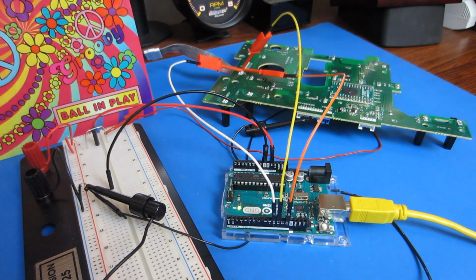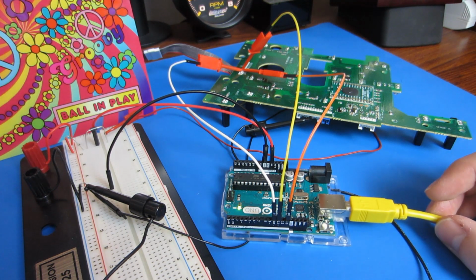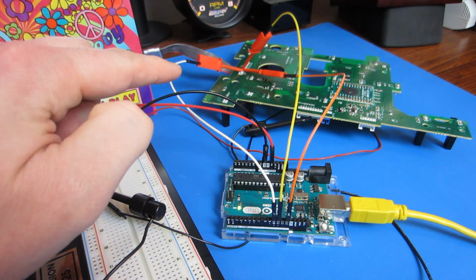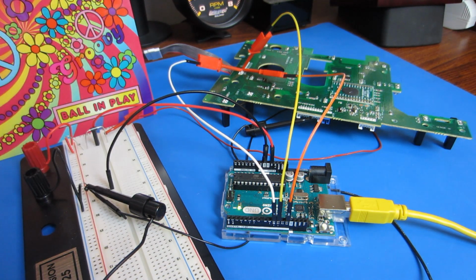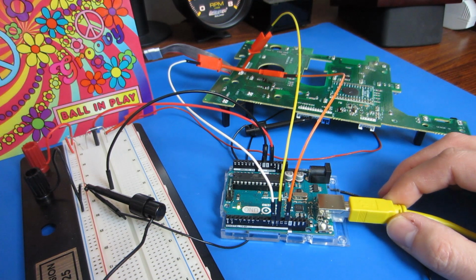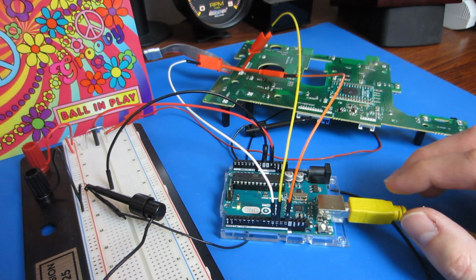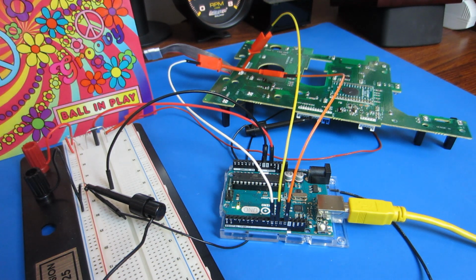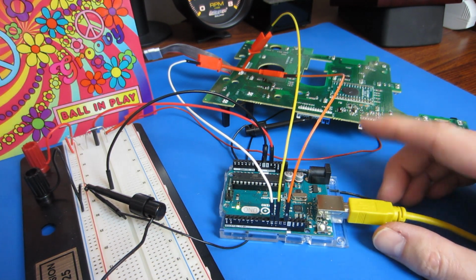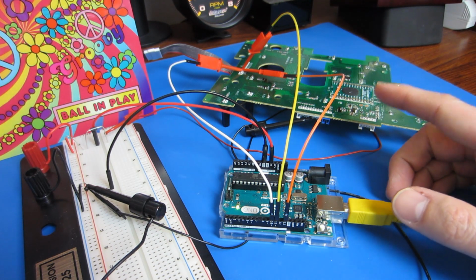I've changed the way the system is powered. You can see I've got USB plugged in. This is going to my PC. I don't have a power supply connected to the breadboard anymore. In fact, the breadboard and the playfield and the backbox are all being powered through the USB connection to my PC. I have to have this USB plugged in so I can see the serial output of the Arduino when it's reading the SPI bus. And you don't want to have external power plugged in at the same time that you've got USB plugged in, or you could fry the Arduino. So the USB connection to my PC, the maximum current, is definitely enough to carry both the Arduino and the pinball machine's playfield and backbox.